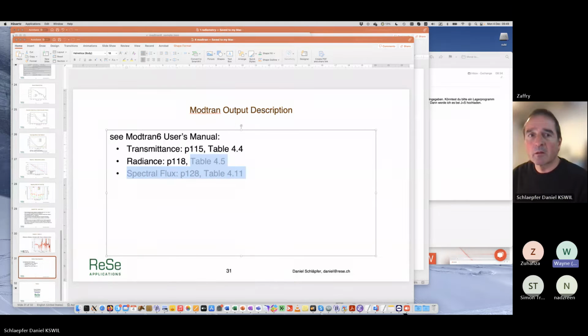I remember other than the standard atmospheric profile, you can also key in your own radiation data or the atmospheric sounding profile. You can key in the real-time data instead of using the standard profile. I think MODTRAN allows getting more representative of the atmospheric condition during your measurement or simulation.